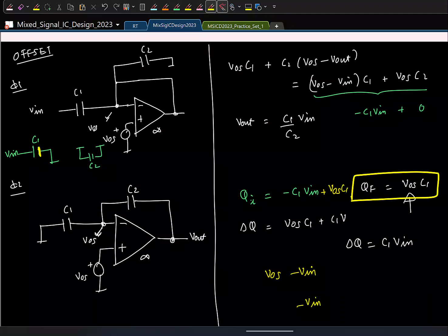1,000 gain. No, so small op amps do not have thousands. I mean, you can make op amps with thousands, but that will take a lot of power. Normally, a non-ideal op amp will have... see, you can make op amps with 80 dB, 100 dB also, 1000 and 10,000 also, but it takes a lot of design effort. And if you wanted to operate at high speeds, ensuring good linearity, it will take up a lot of power. On the other hand, designing a simple common source amplifier or a simple differential amplifier with a gain of 10 or 20 is simple. That's much simpler, right? And it will take much lesser power. So which means for the smaller power, you can basically get a higher gain.